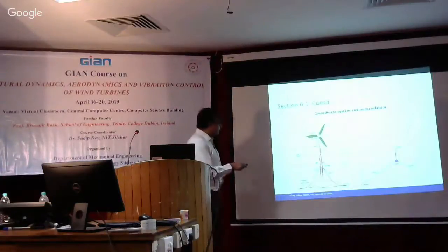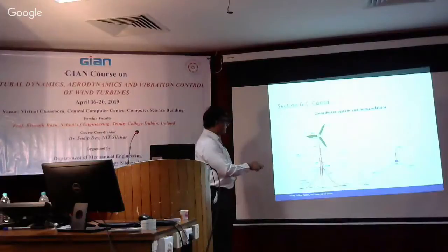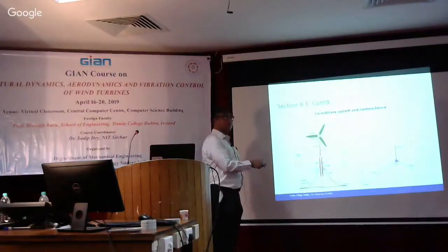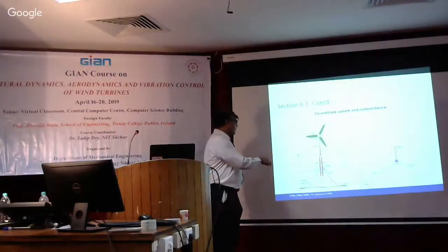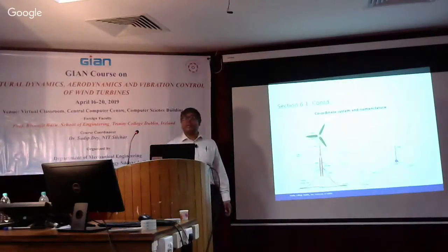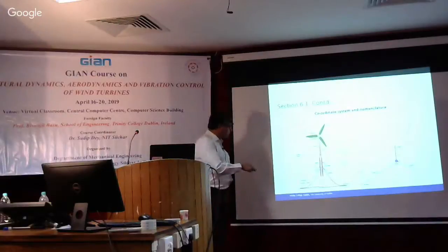And then it's connected to this cylinder, which is a spar, which is an extended cylinder. So this is really the support structure, and they are eventually connected to the mooring cable, which is lying on the seabed. And let me tell you that seabed interaction also is very nonlinear. You can have reflection of waves coming from the cable and affecting the spar as well.